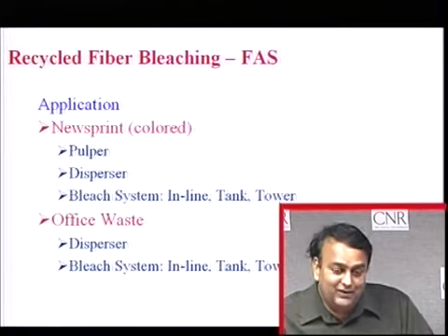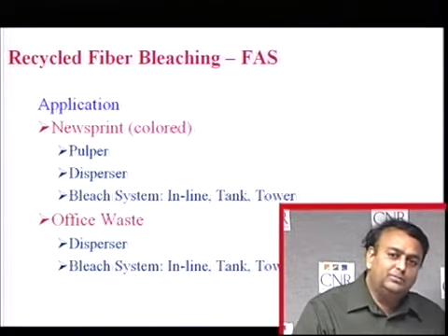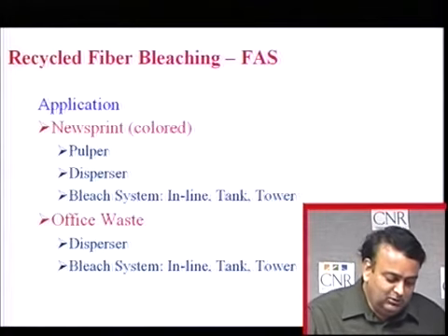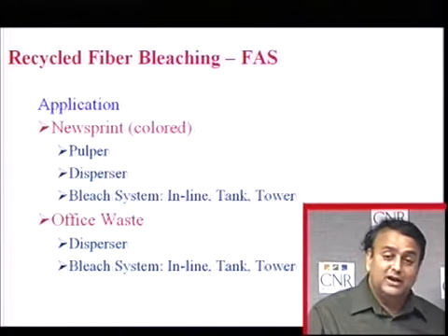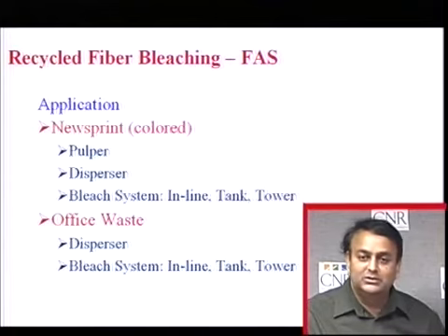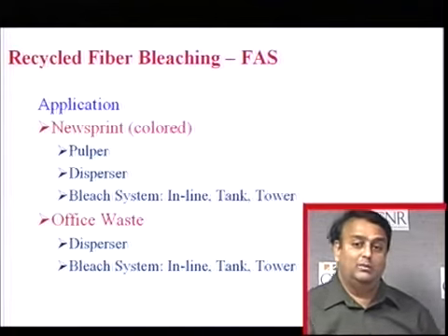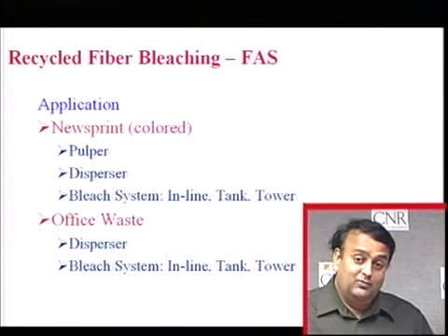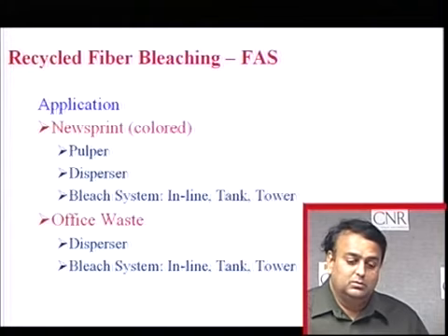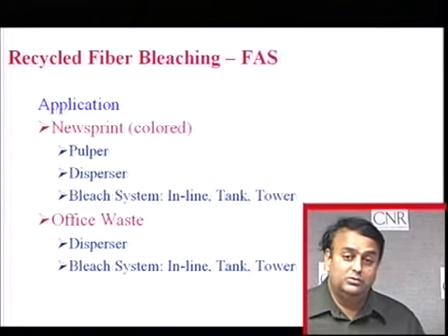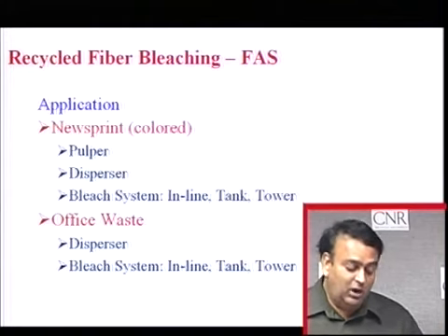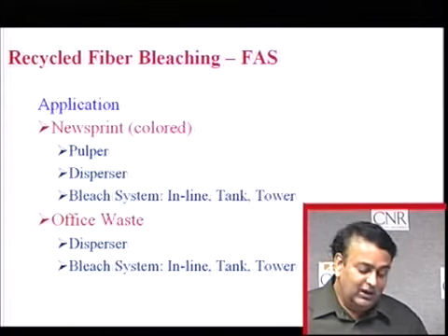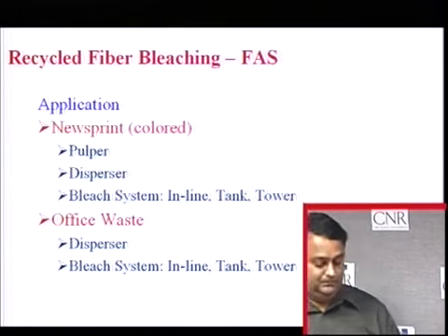Where do you apply FAS? On colored newsprints, there are pink color newsprints and slightly blue color newsprints available. There you can use FAS to get rid of the color in the pulper, disperser, inline, tank and tower bleaching. Where it's more popular is for office waste color stripping. For stripping red, yellow, blue dyes, FAS works very well. So it's again added at the disperser and also inline, tank and tower bleaching.